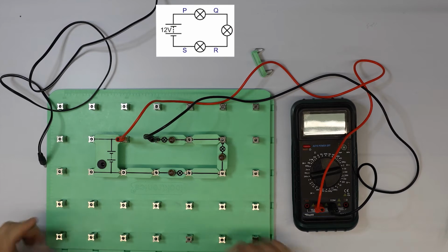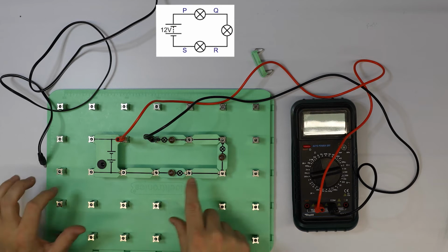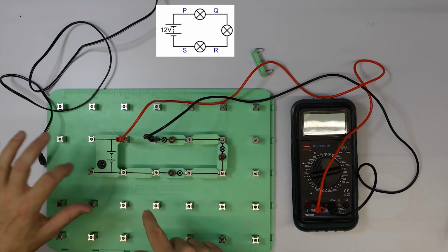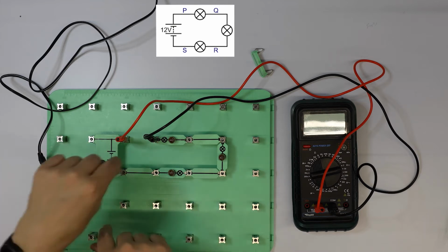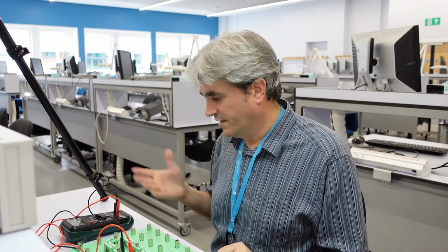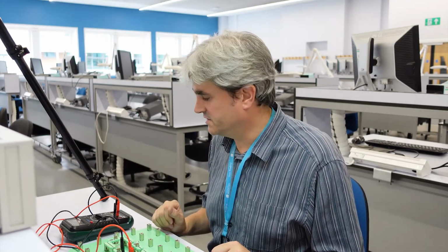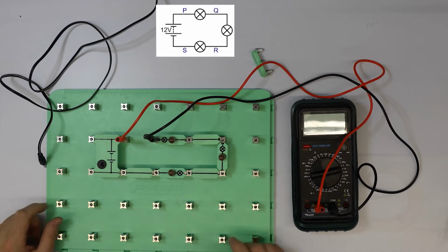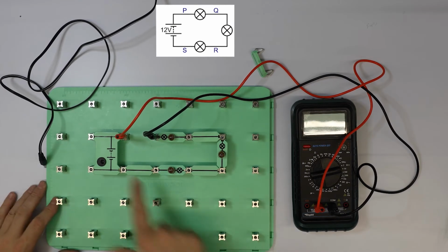And it's really important when you're setting up for a current measurement that you're not causing a short circuit anywhere in the circuit. Because basically, if I connected the current meter directly across the power supply, I would see a large amount of current going through my multimeter, and that would cause the fuse to blow. Now, it's not a big deal. We can replace that fuse, so someone else can use it after we've made that mistake. But it's a slight pain, and obviously, it speeds up the experiment if we're not having to replace fuses in multimeters. So we always have to check our circuit to make sure that we've not got any short circuits.